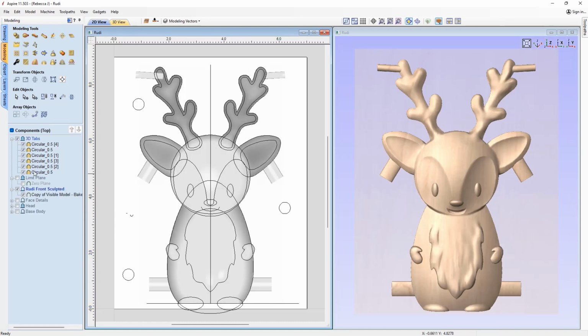Okay, so we spoke about the 3D tabs and the dowel positions, how we keep everything aligned. Now, when we're machining our top side and our bottom side, wherever we position our model within our material block, whatever that centre is, that's where the centre of the tool is going to go when we cut both sides, okay? And that could present us with the cusping effect because of the fact that we're using a rounded tool in our finish pass. When it gets to that centre, we could be presented with a seam.